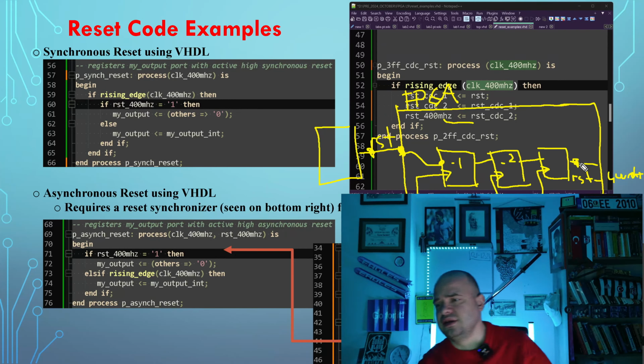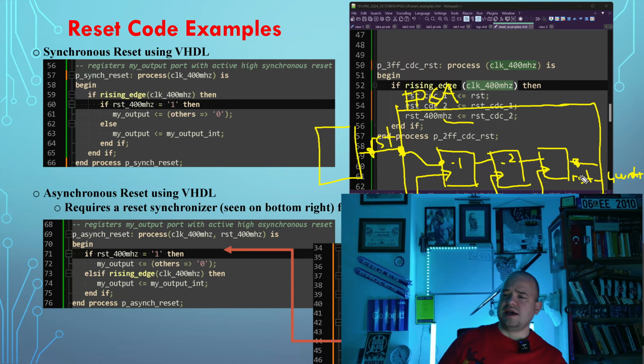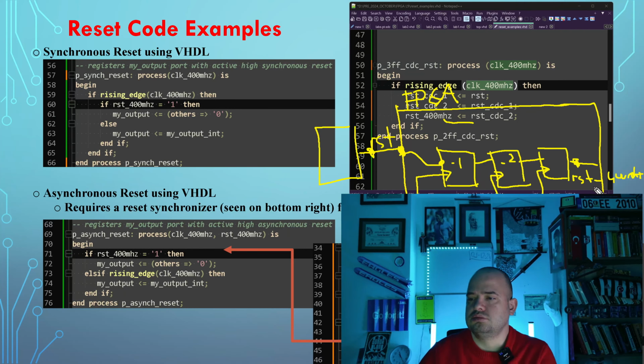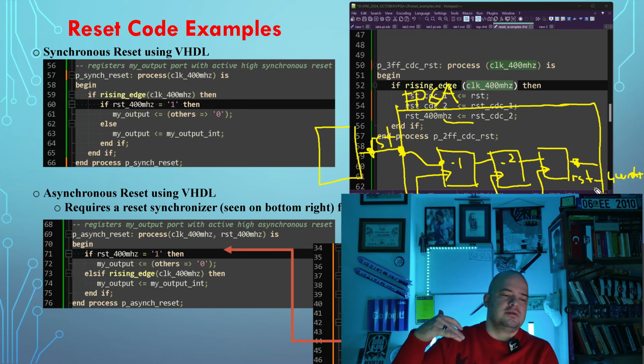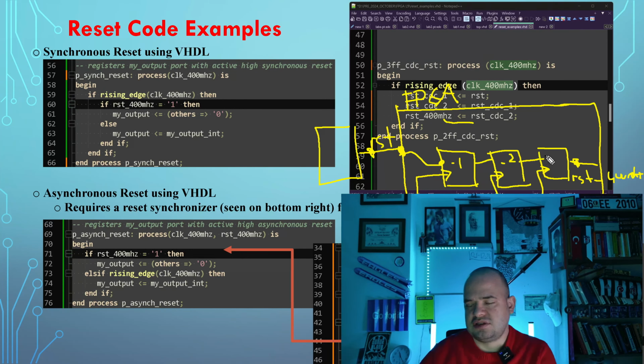Then you can calculate the MTBF value of this. Actually, this signal after those 3 flip-flops could still be metastable, but that MTBF value, mean time between failures, is really high, really long. It is like more than, let's say, 70 years.